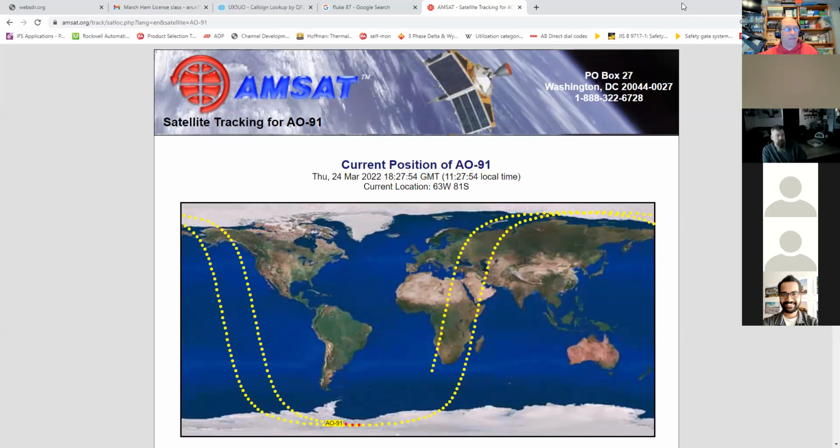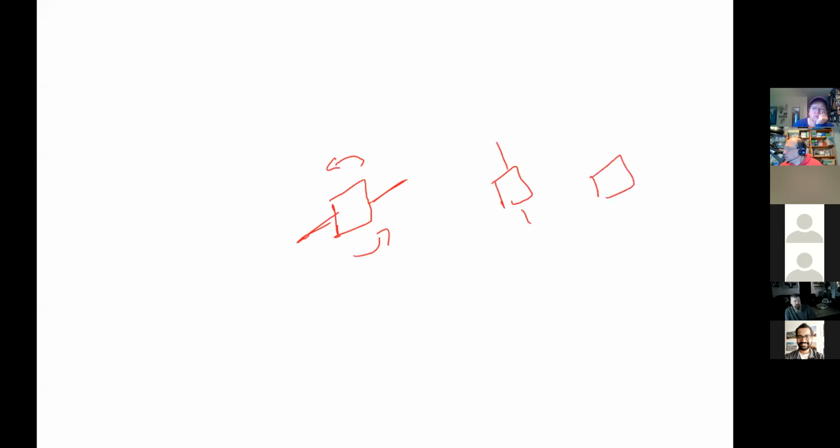Spin fading of satellite signals. Satellites, in order to keep their position in space, are typically tumbling. They're spinning. And if a satellite, let's say that looks like this, has an antenna system that looks like this, as the satellite is rotating in space, sometimes the antenna will be pointed like that. Sometimes the antenna will be pointed like this. It will be in different orientations, and you will actually have fading when an antenna, for instance, becomes eclipsed. If I'm looking at the satellite, the antenna becomes eclipsed by the satellite temporarily. That's known as spin fading, as the satellite rotates out of view.